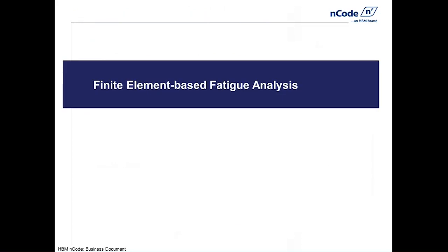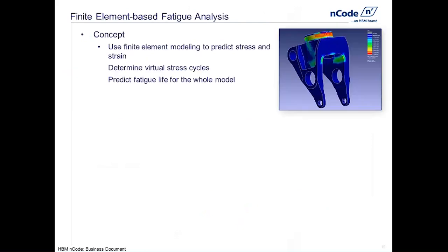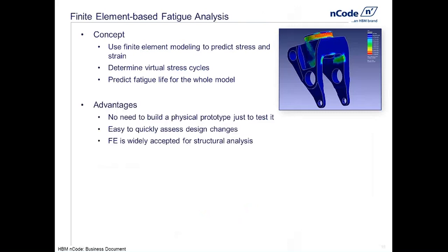So the second thing I'm going to talk about today is performing FE-based fatigue analysis calculations. The idea here is that we're going to use FEA tools to predict stresses and strains. We're going to take those stresses and strains that FEA solved for us, and then use design life to determine virtual stress cycles. So we're taking static stresses from FE and using design life to cycle those stresses, on a full model basis. We're taking stress plots and turning them into full model life plots.